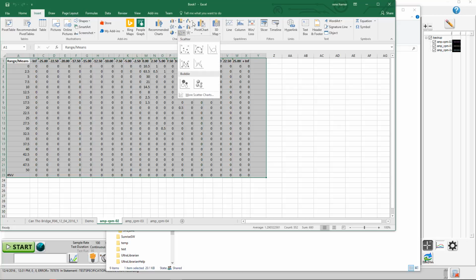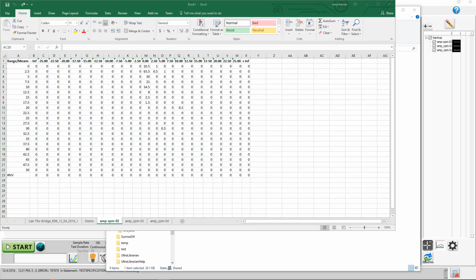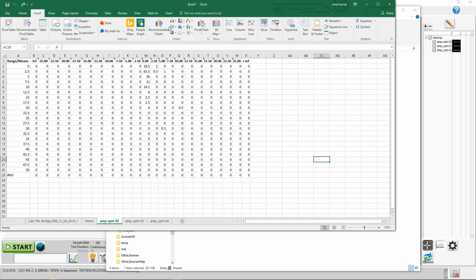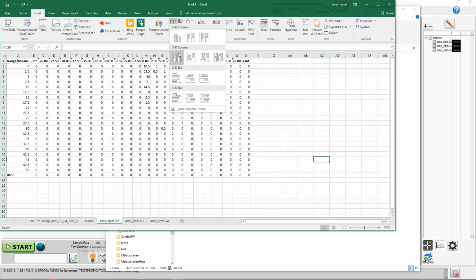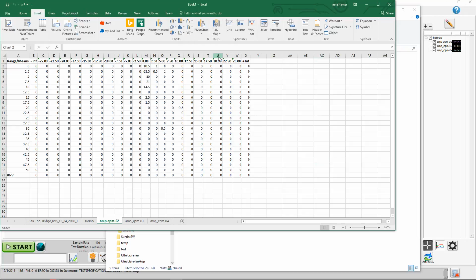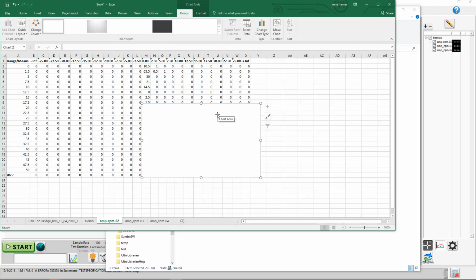It shouldn't be much of a surprise what we are seeing here. Let me do that back. You see that all the cycles are counted over the mean, and we have a large cycle count because we have a vibrating system. We want to see histograms, and we have a 2-dimensional histogram. That completes my demonstration of rainflow. Thank you for your attention.